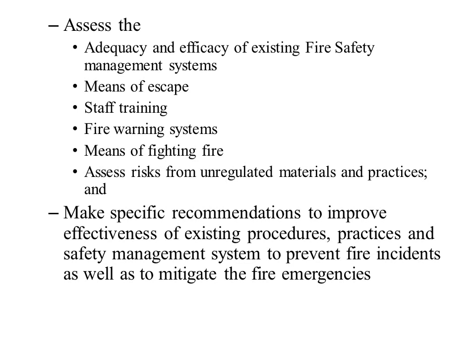Open all the doors and windows. And even after doing all this, if the gas smell persists, we should call the emergency service or the gas distributor or a person who is qualified to take up such jobs. Of course, this is very important: do not operate electric switches, because if there is a gas leakage in that area, it may cause a fire.